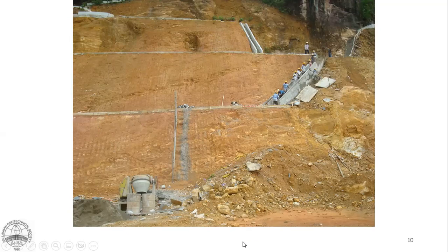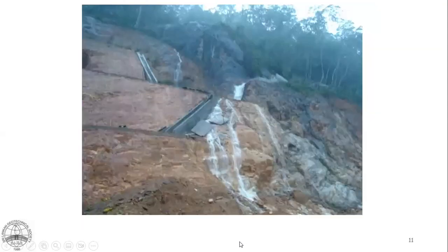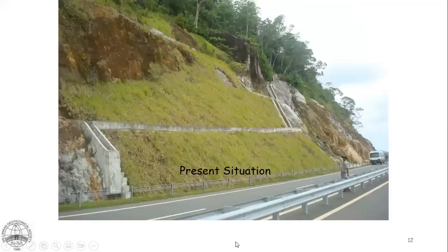implementation of the drainage solution, and if the drainage solution is not complete, during a heavy rainfall that occurred at that stage, you can see how much water is flowing in an uncontrolled manner. If these surface drains were not properly installed, there will be that kind of flow all over the surface. If you remember, I showed you a picture earlier, where this kind of uncontrolled flow of water created a landslide after a few years. So this is before implementing the full drainage measures. Some parts of the berm drains and the cascade drains were not done by that time.